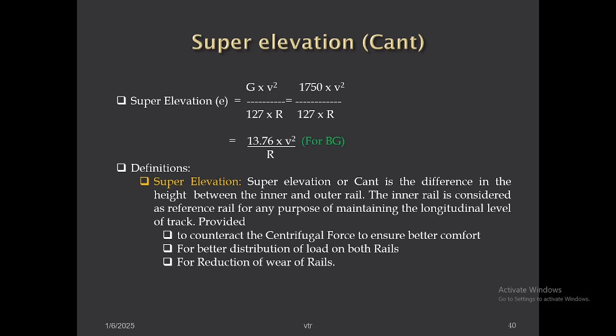Because of providing cant, the tilting of the track balances the centrifugal force, and finally the resultant force falls within the base. That is what the definition says.